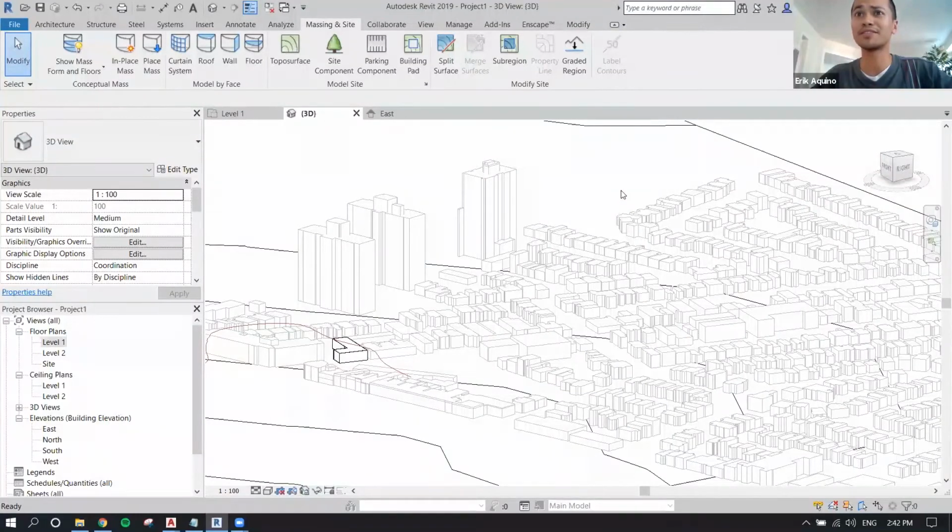This is the way I was taught. So if you know how to do this, you can download DWG. Just this DWG has flat contours. Contours in the DWG, they're all at elevation 0. So if you want contours to be in 3D space with proper elevations, then you have to use ArcGIS.